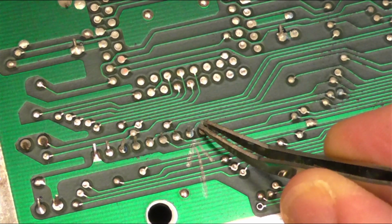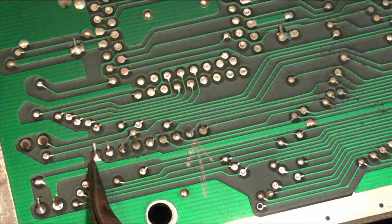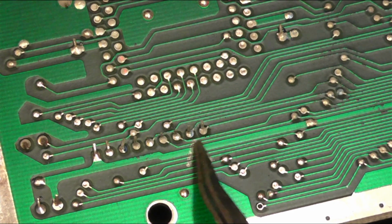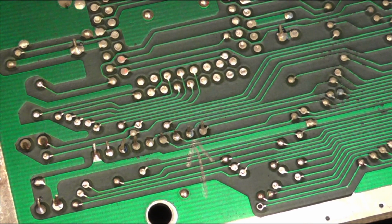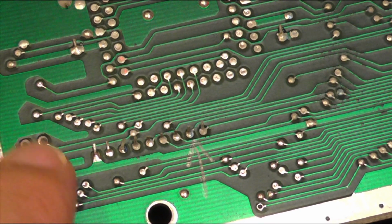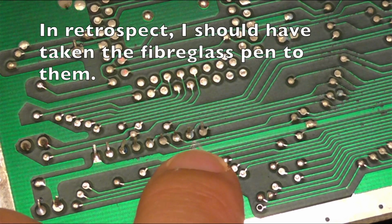This is dull as ditch water over here. You can see there's the VCC connection, that's the square pad, and then the round ones here are obviously all the different ones. I'm not sure if they are address or data. I'd guess that they are address over on this side, but they look awful, to be honest. So I think we need to clean them up and reflow them anyway.